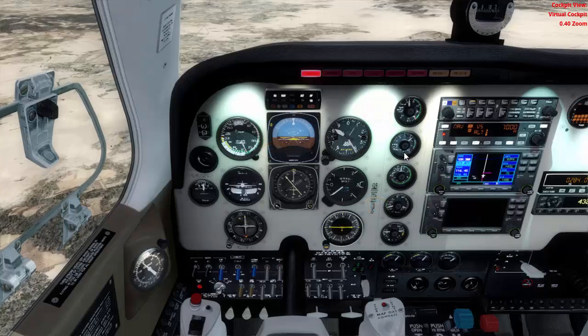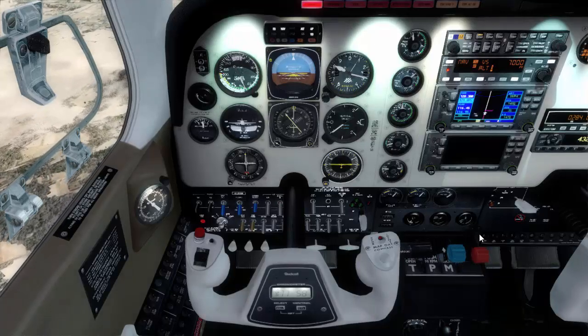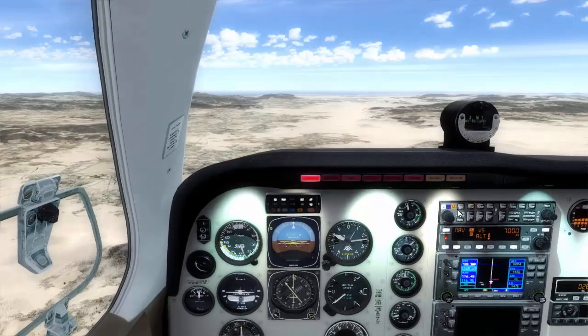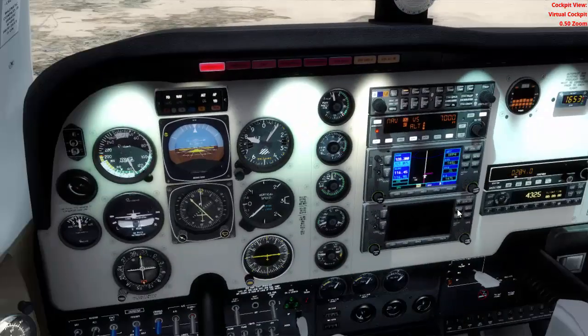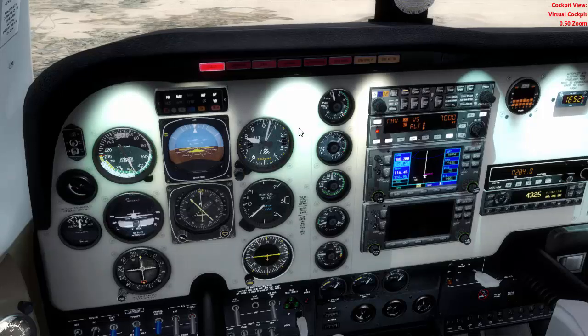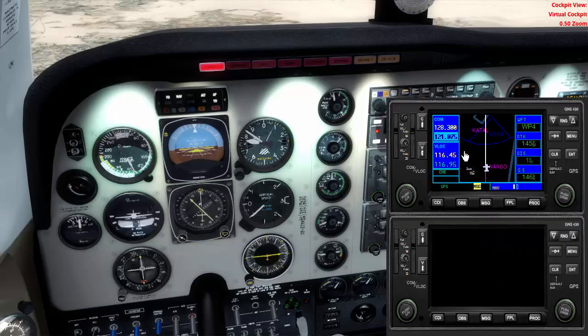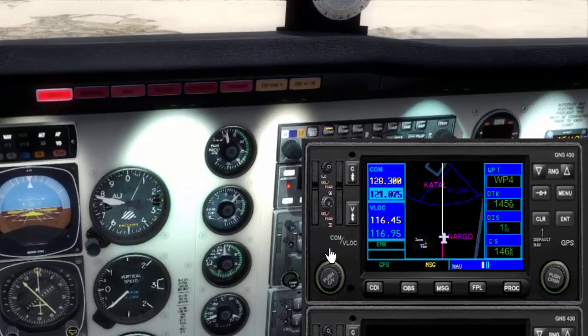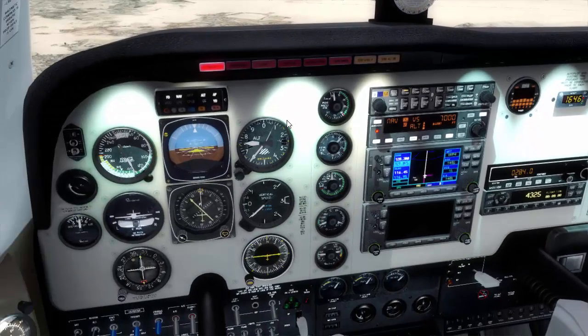So I'm giving you also some eyes there, as you may have seen, telling you the gauges you need to monitor. I will control more the revolutions, and I will cut more the speed for the engine, because basically we are gliding. We are descending with the own weight of our aircraft, so we don't need to put more engine power, and it's completely normal that we have an extremely lower value in the manifold pressure gauge. We don't need to put power because we don't need to fight against gravity, okay. We are using our own weight to glide. That is what we are doing. For that reason, you have a lower value in the manifold pressure instrument, okay.